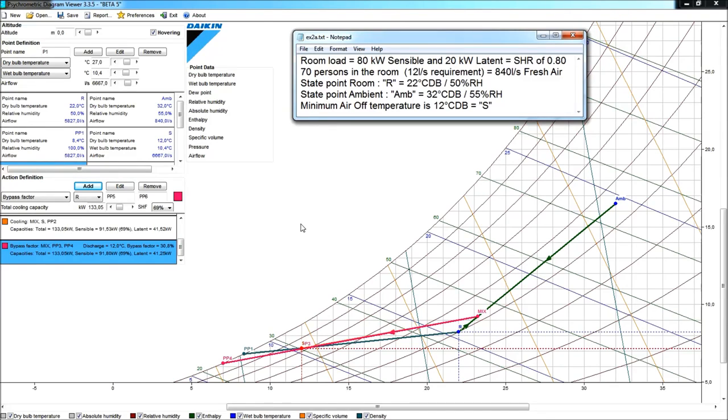Needless to say, we can reduce the load again if we would have the means of, let's say, installing a heat exchanger. Or that heat reclaim ventilation device could have a total heat exchanger like in our VAMs, or could be another means of cross flow where you would exchange the exhaust air and the fresh air, and thus have a preconditioning of that fresh air and less load in your room.